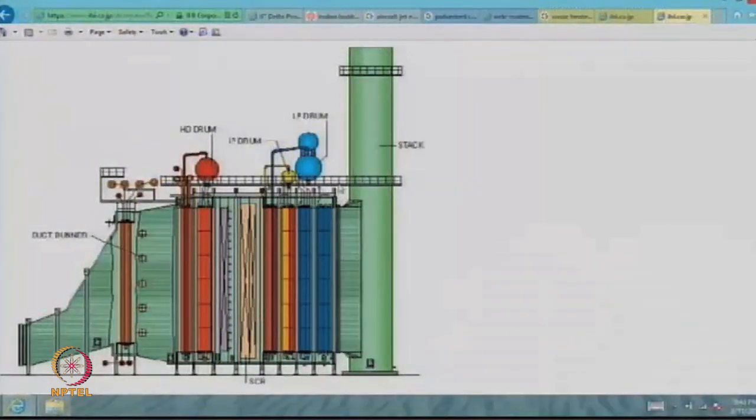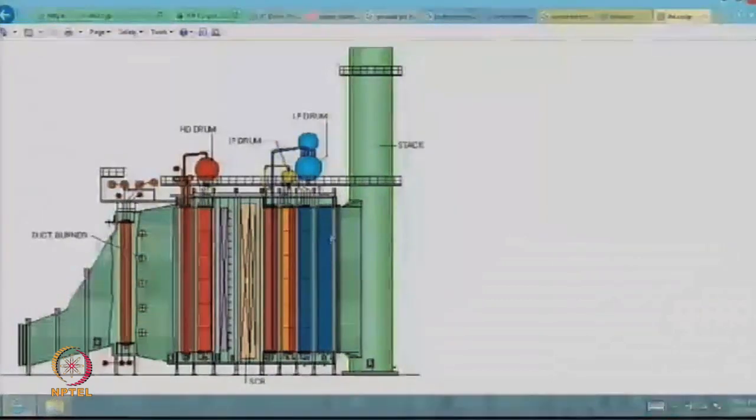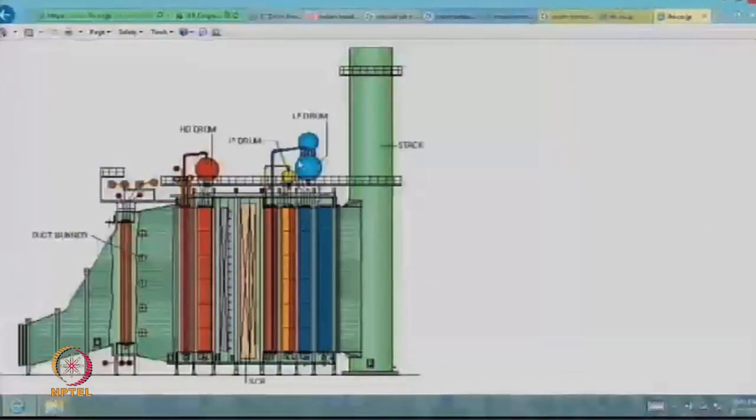The cold water comes in at this end, gets heated up a little bit, then comes out. Then we put it through another set of tubes, we evaporate it. Then we take out the vapor and put it through this and heat it further. And all of this is done at a lower pressure because then lower temperatures are possible. At another point, we put water at a higher temperature, then heat it up, make it a vapor, then again evaporate it and take the vapor and heat it, and out it comes at this end.